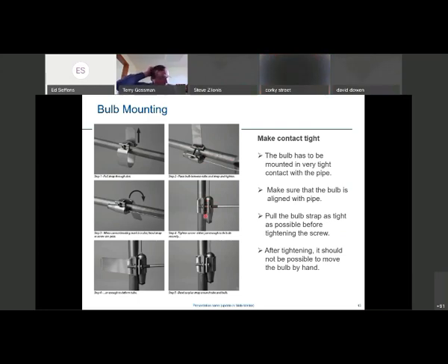Here we're taking a look at the vertical side, where the bulb is attached with the capillary tube feeding down into the bulb itself. There's a lot of controversy with that, where people say it's best to have the capillary tube on the top of the bulb rather than on the bottom. I prefer having it on the top, even though with some manufacturers the capillary tube extends a portion inside the bulb itself, so you can locate it either with the capillary tube up or down.